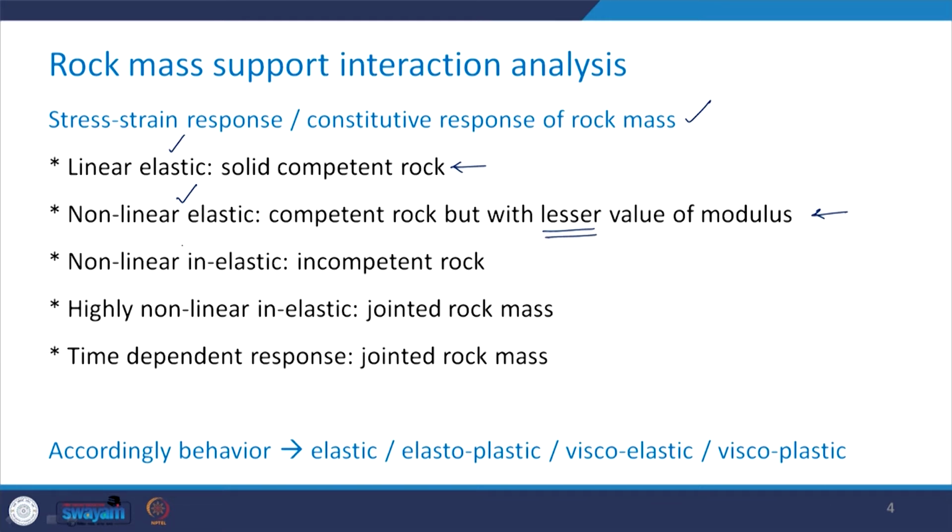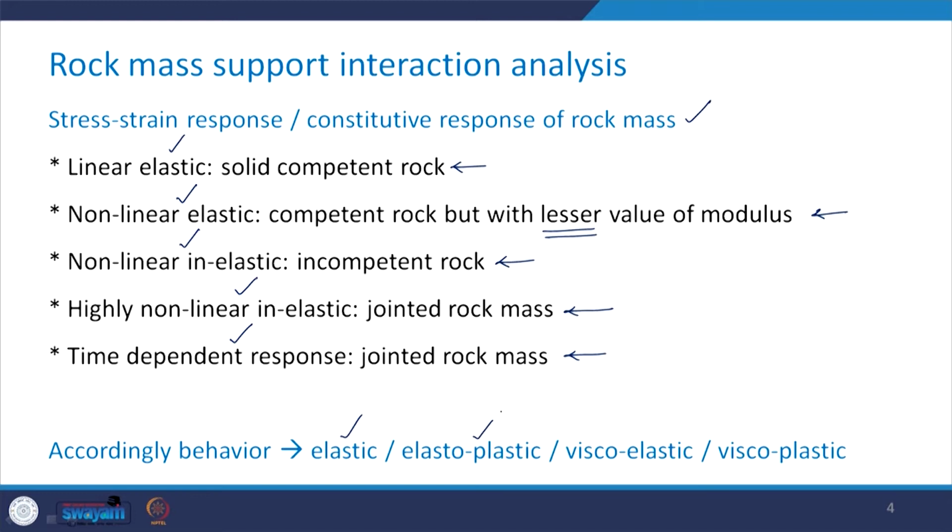It can be nonlinear inelastic in case of incompetent rock, highly nonlinear inelastic in case of jointed rock mass, and then you can have a time dependent response also in case of jointed rock mass. Accordingly, the behavior of the rock mass would be either elastic, elastoplastic, viscoelastic, or viscoplastic.